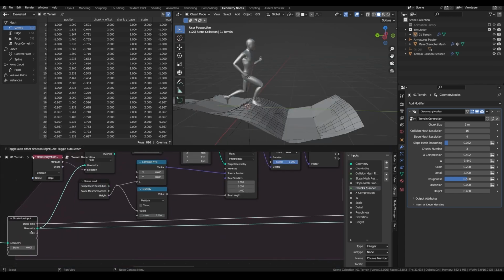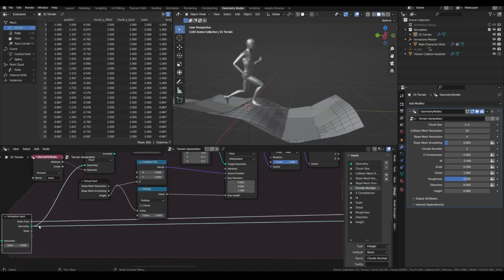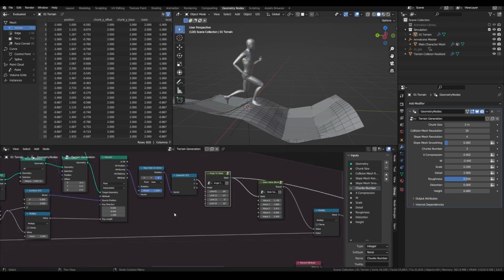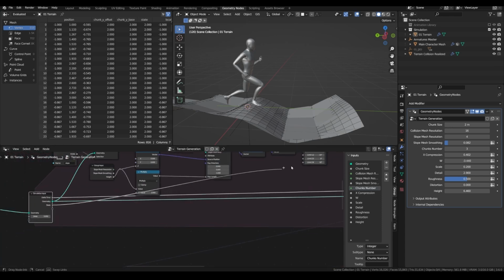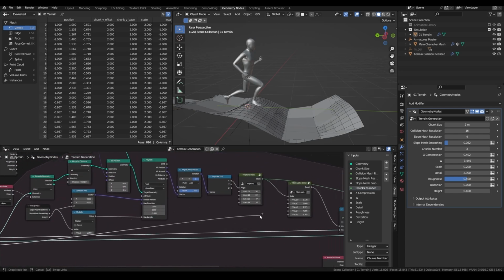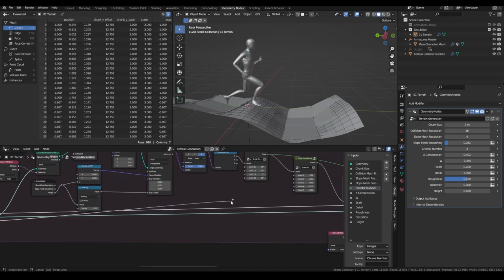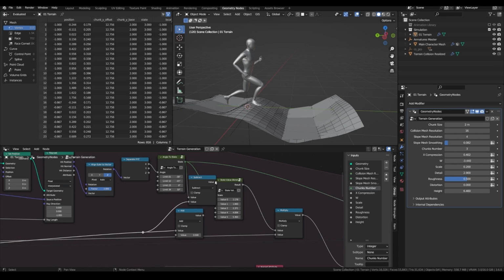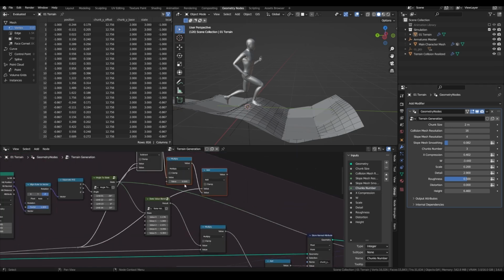So here, because we already set the state value as a simulation input and output, we'll be able to blend the new state value computed each time with this value, which is the previous state. And basically, how it works is we are going to add to the previous state the difference between the new state and the previous state multiplied by some factor. And this right here is a really simple version of an attack and release. Depending on this value, the new value will have more or less effect on the previous value.